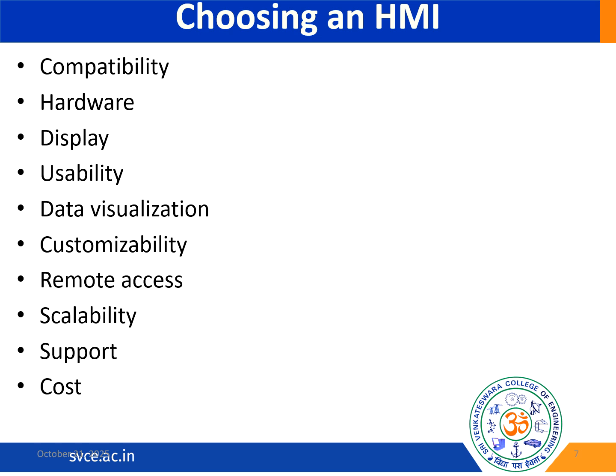So here we have some adaptabilities, where we ensure the HMI is fully compatible with the control systems, communication protocols like Modbus, OPC UA, and data formats used by equipment. It is used for seamless integration, where it minimizes configuration overhead and ensures reliable operation. So these can all be considered under system compatibility.